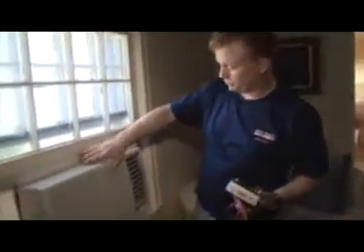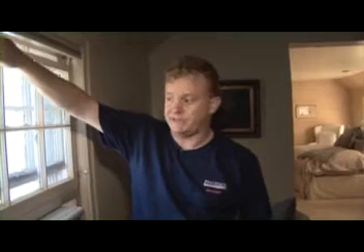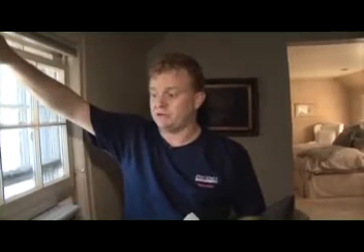And upstairs in the master bedroom, there's yet another problem with air leakage. Because their central air conditioning is not doing a good enough job cooling the upstairs, which is a common problem, they put in a window unit into their windows. But as a result, basically this window's wide open, and air's rushing in right now because of the blower door pulling it in. So this is like keeping a window open in their house, which is a big energy waste, and it's also going to affect their comfort. It's going to make them have to run this window unit a lot longer.